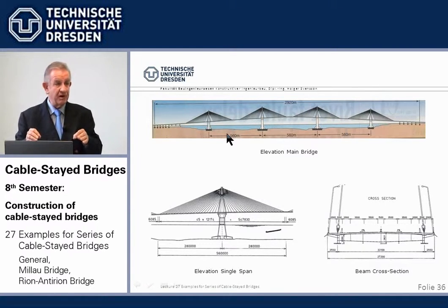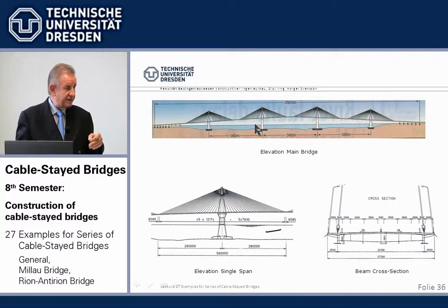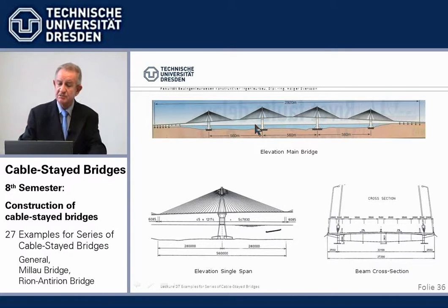Millau, they were very high. Okay, cost money. But with sliding forms or jumping forms, it's not so bad. But here, we had to make them fit against the earthquake, which made them per unit even more expensive. And the more expensive the piers become, the more overall economic it is to make the spans longer. I think that's a very basic issue.